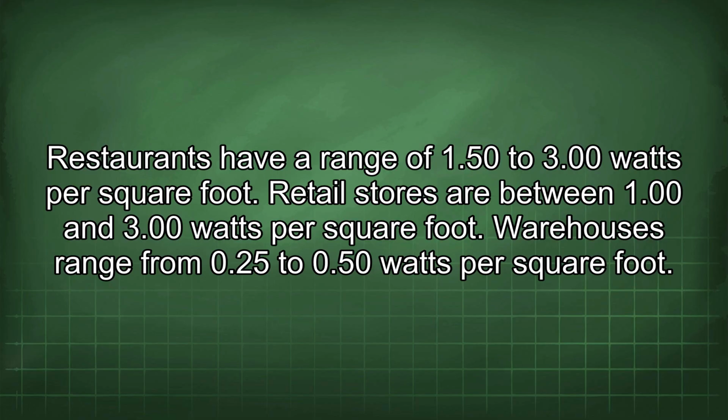Restaurants have a range of 1.50 to 3.0 watts per square foot. Retail stores are between 1.0 and 3.0 watts per square foot. Warehouses range from 0.25 to 0.50 watts per square foot.